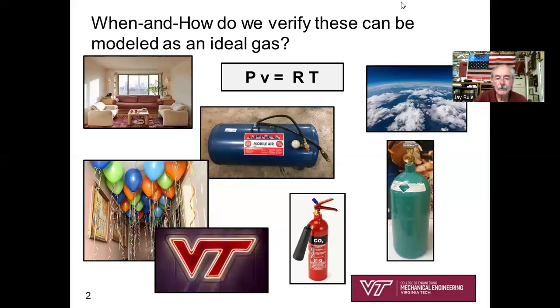Well, we recognize all these situations as commonly recognized gases. What we would pray for is that for most of the ones I'm showing here, absolutely, we're going to be able to treat all these images as ideal gases. Let's say P times little v equals RT. See how that can apply to open systems and closed systems alike. P times little v equals RT. Remember what R is? R is R bar over the molecular weight.